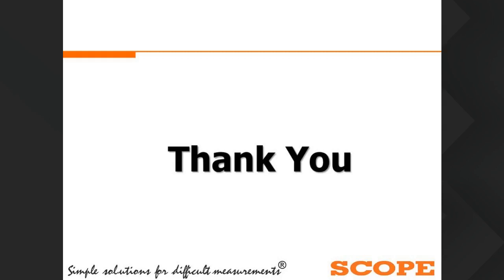Yeah. The last question in the chat box is from Mr. Deepak, who says, can we measure the magnetic balance? Actually, sir, magnetic balance is practically just a checking sort of thing. We are never measuring how much the magnetic balance is. Generally, for the magnetic balance test, we give a small voltage, any voltage you can give, into the middle limb.